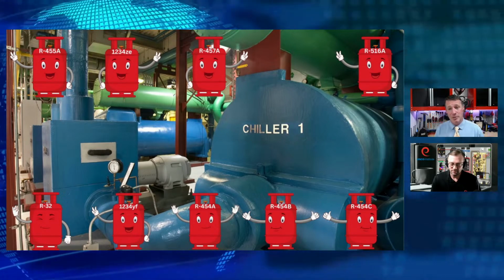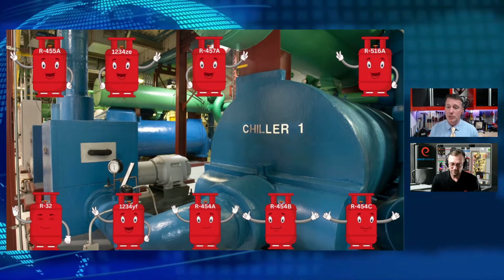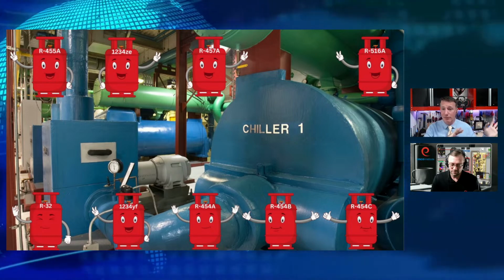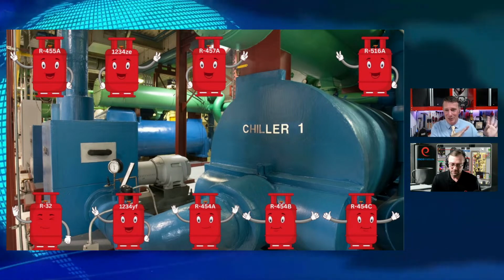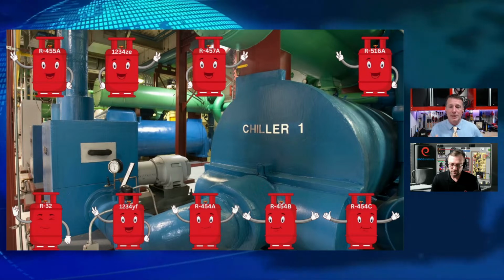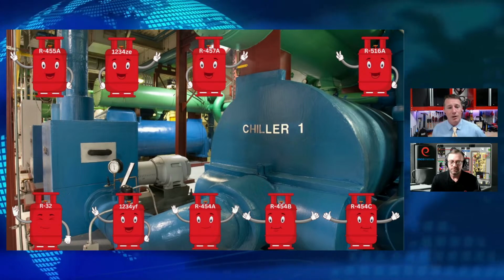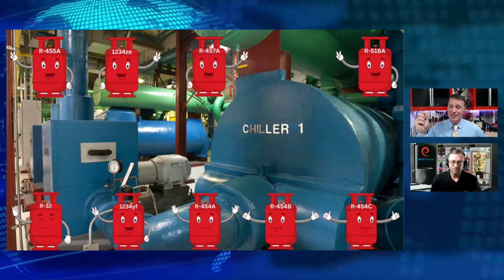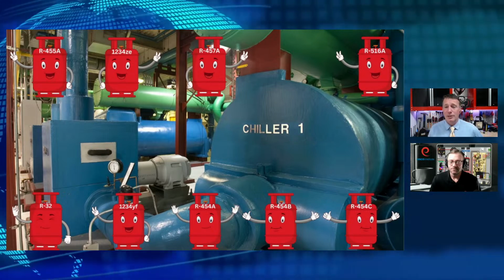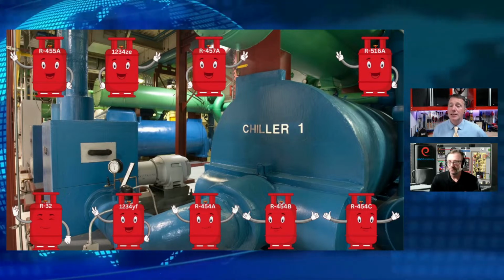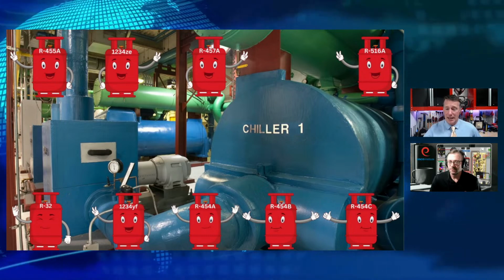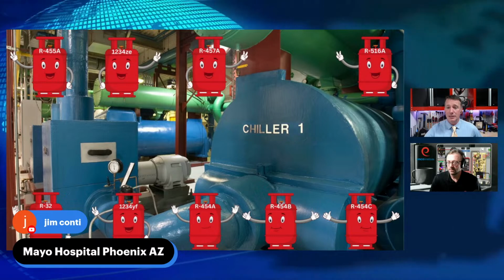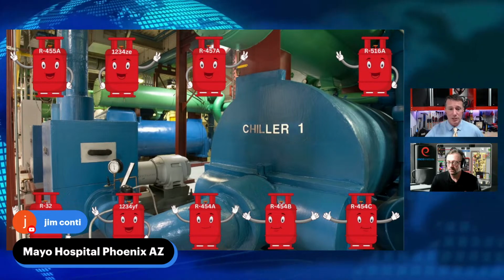So our new acceptable refrigerants that we're going to see out of all of this, our low GWP refrigerants, if you're not already working with things like ammonia or CO2, which is a different class, they've been around for a long time already. They're not new refrigerants. We're talking about some new refrigerants going into these systems. We're back to talking about R32, we're back to talking about 1234YF. We're now actually going to add in an additional one, which is that 1234ZE, right? It's another one of our HFO refrigerants that is going to be utilized in a lot of these lower temperature and sometimes lower pressure applications.